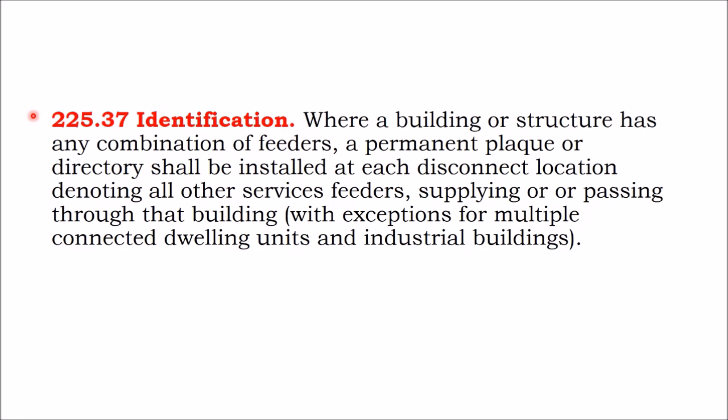And that might become more of a mandate in the future, where we start to see philosophies of rapid shutdown for solar start to be applied to battery banks and stuff like that. But then again, having one switch that de-energizes everything in a readily accessible location doesn't sound like the best solution either, because now you could have pranksters come around and easily power down your whole building, and that's not suitable for safety for that matter either. Where the design is going to end up, I don't know.